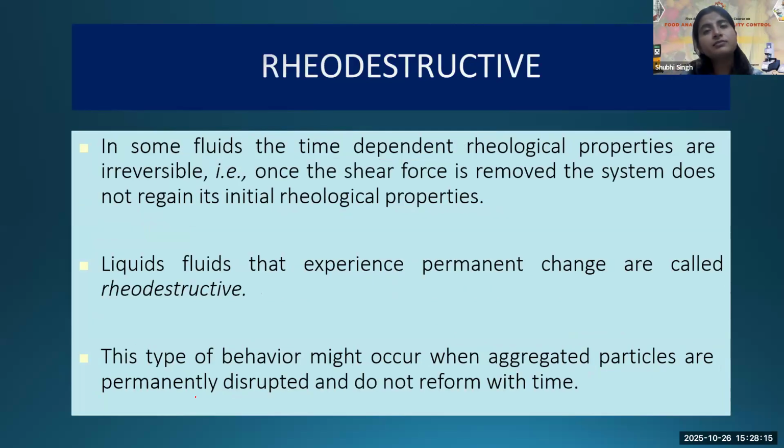And there are some liquids known as rheodestructive. In some fluids, the time-dependent rheological properties are irreversible. That is, once the shear force is removed, the system does not regain its initial rheological properties. So after the application of an external force, when you remove that force, they will not regain their initial rheological properties.